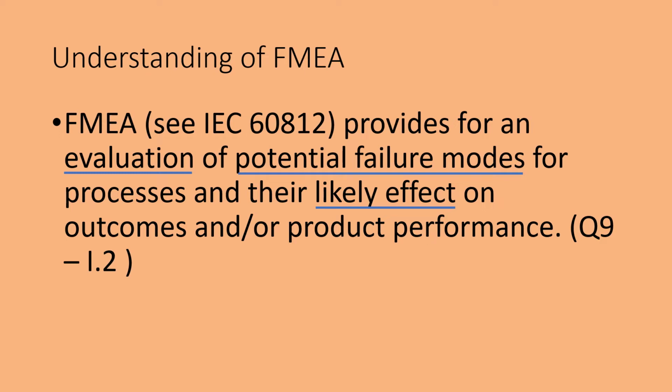The FMEA tool is very useful when you initiate any new installation and qualification of equipment, or a change control for any changes in men, machines, methods and materials in GMP. The guideline prescribes that FMEA can be applied to equipment and facilities and might be used to analyze a manufacturing operation and its effect on product or processes.